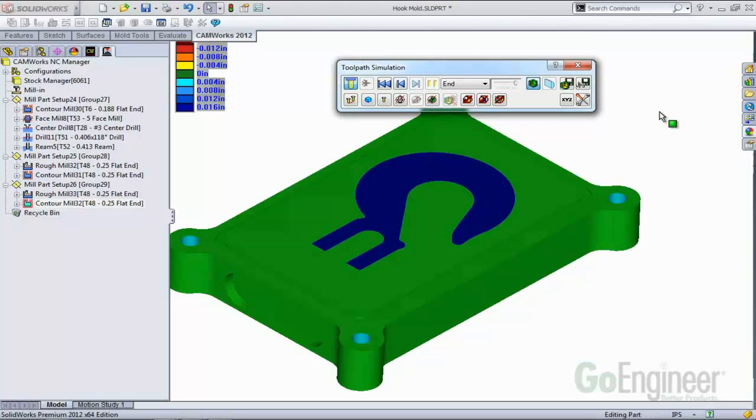And if they did, then we probably wouldn't ream them. We could bore them, or most likely what would happen is the designer would say, cut them to whatever size you need for that pin size. So it makes sense to me that those are blue, because CAMWorks isn't going to create an arbitrary tool to match the diameter of the hole.